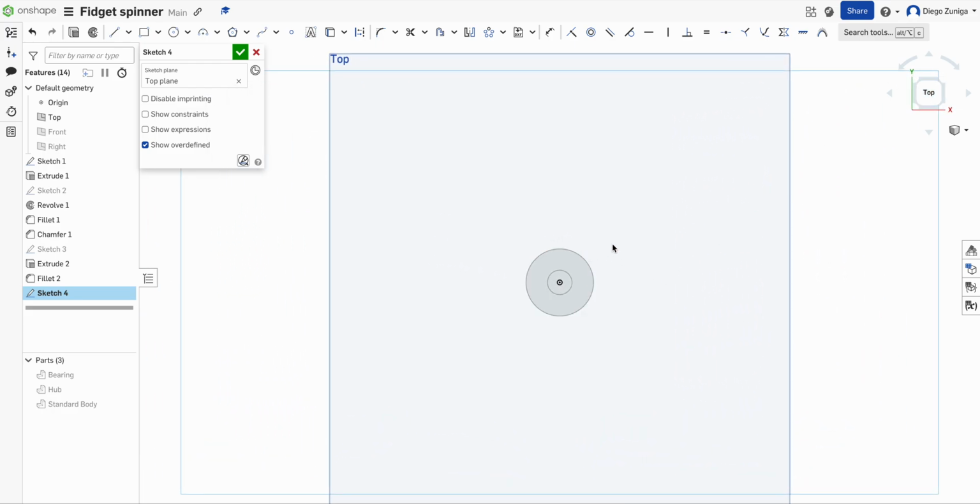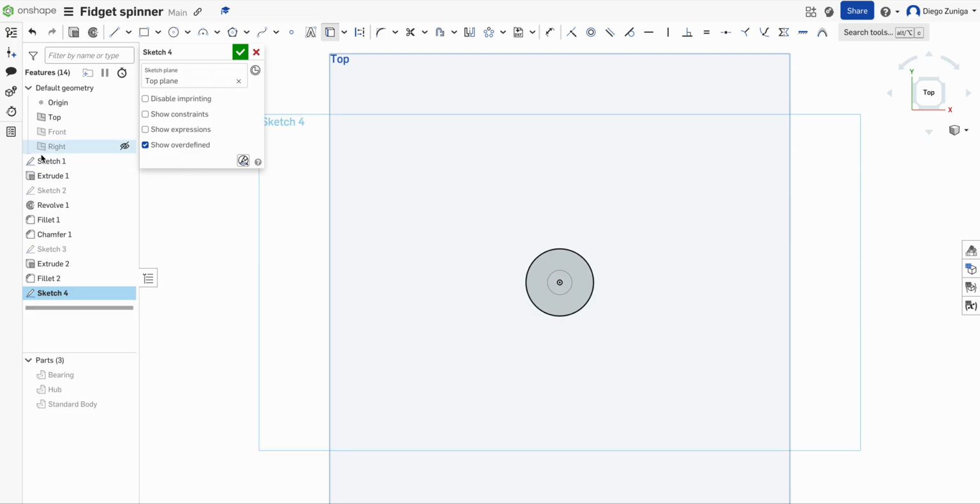I've done a version of it that's kind of like a nuclear logo. So again, I made sketch one show up in here. Again, we're going to use the project tool. I'm going to select this circle, and I'm going to hide the sketch one again.